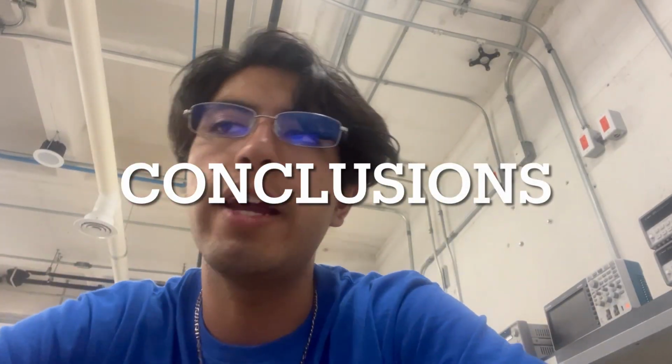Something important that you need to know is that Euler's formula, also electromechanics and Kirchhoff's law, are important to know because they describe the behavior of the motor, but it's not indispensable for this project. So you can try it in your house, try with this program that we're going to give you, also the drivers and the motor that you have. It's important to know that motors with encoder have different connections, so you will need to check that before, just in case, to not damage the encoder sensor.